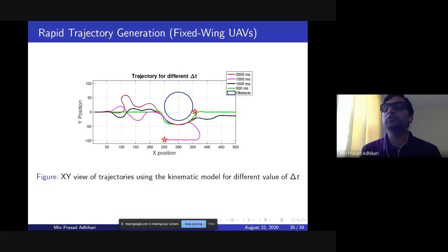Of course, 100%. The Raspberry Pi example is just one example to show that even an onboard computer can do this. But if you have an expensive quadrotor UAV that costs thousands of dollars, then you don't want to put a computer like a Raspberry Pi on it, or maybe you want to opt for a better one. And you will definitely have to think about temperature and heat management. Maybe you'll have heat sinks and an air cooling system, because it's a UAV flying, so there is lots of air flowing around.